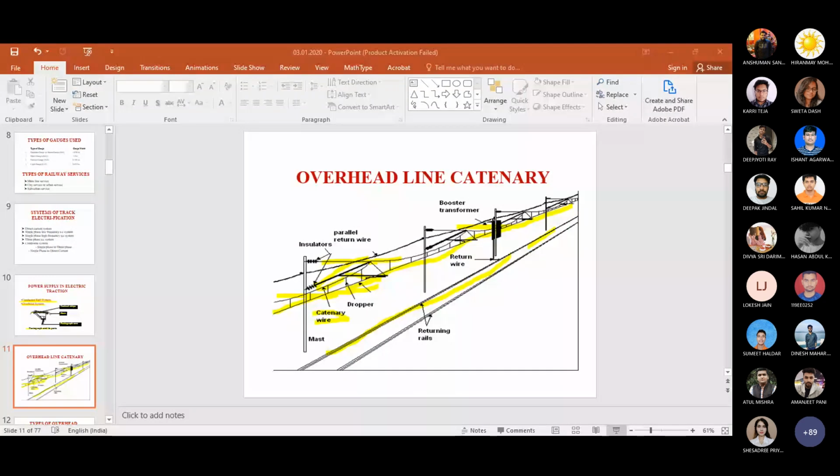If you see the cross-sectional area of that fifth wire, it is quite less compared to the other phase wires. What is the purpose of this fifth line? That fifth line is for street lighting. In your street, on the RCC poles, you can see different lamps connected, maybe halogen, sometimes fluorescent, and now in most cases LED lamps. That street lighting is connected to the fifth wire, and the sixth wire is your neutral wire.